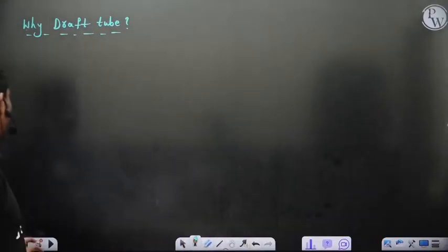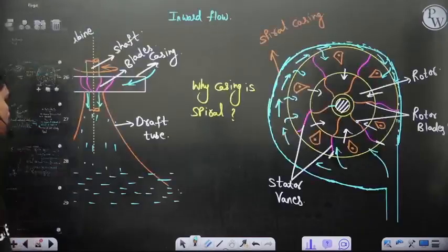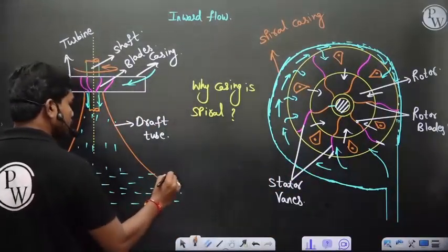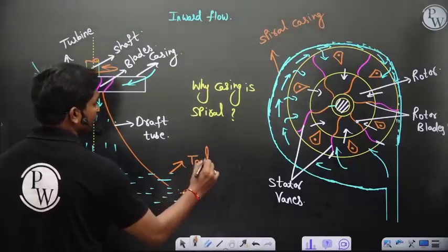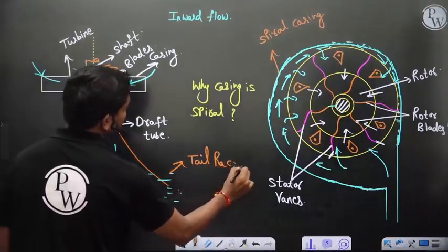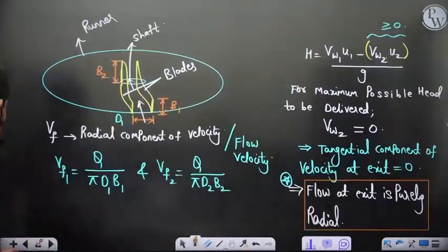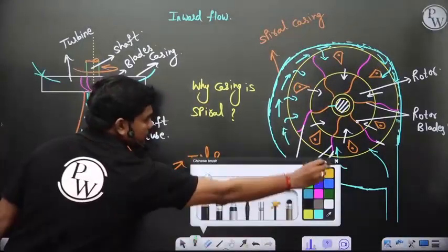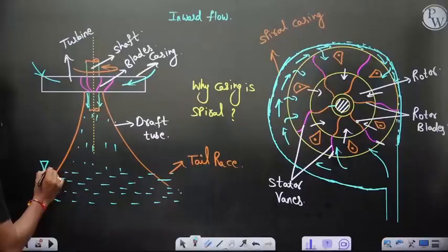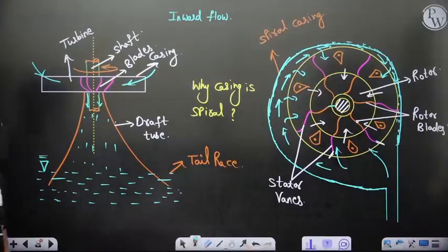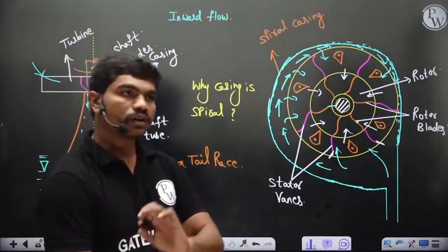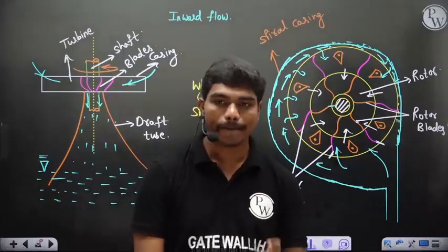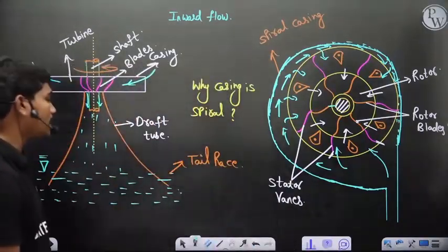Look, this is normally called the tail race. Now here the pressure is atmospheric pressure. So normally you cannot bring the fluid to very low pressure because there is an issue of cavitation, you know this. Okay, but because of this, what happens?